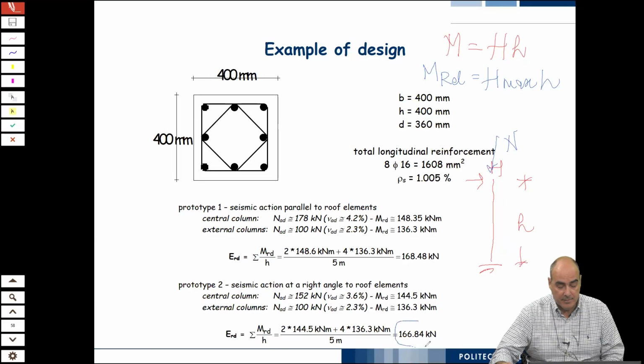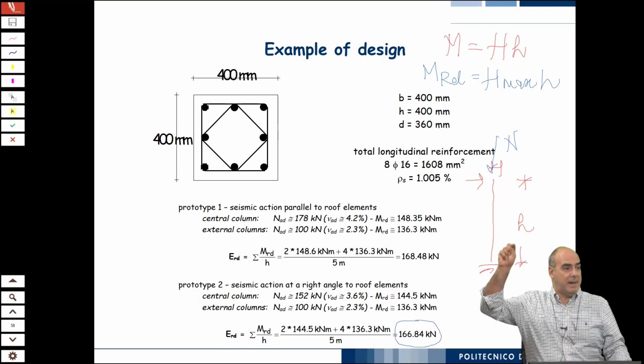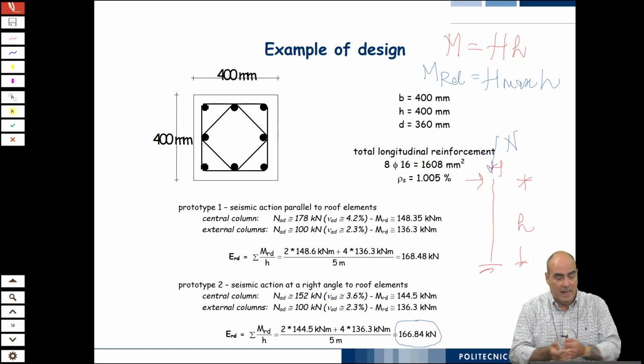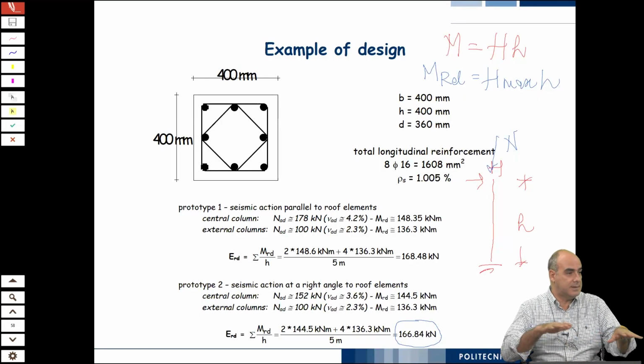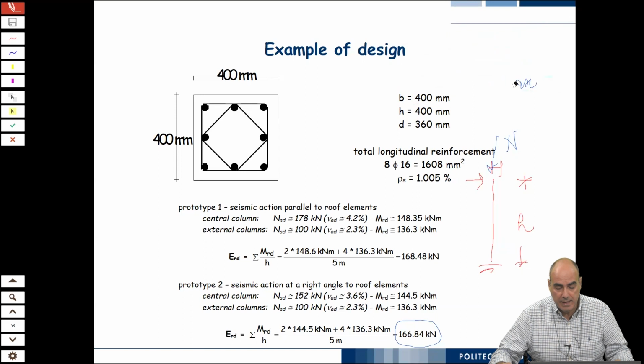This number here, you can see the maximum lateral force, was a useful number for us because we had to design the experiment. So we had to say which is the capacity of the actuators that we have to use in order to apply the force, because we expect this maximum force, which is 16 tons. Since we were applying it with 2 actuators, say 8 and 8, to stay safe we used 10 tons actuators, something like this. So this is the reasoning that we made.